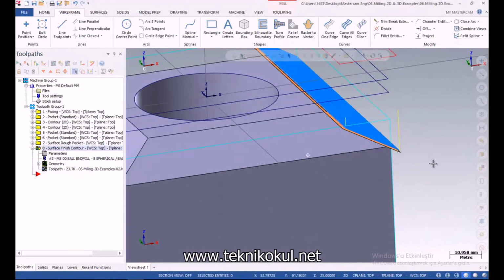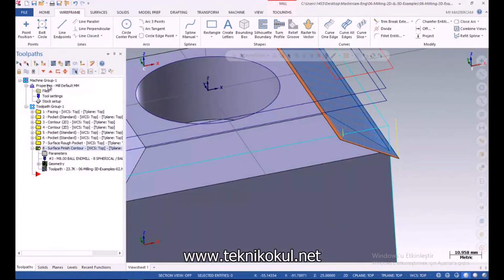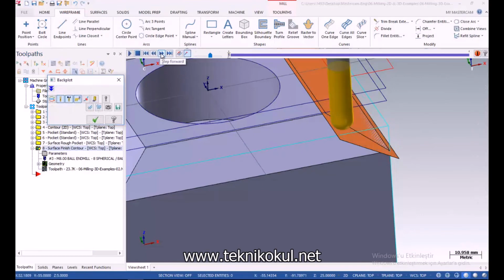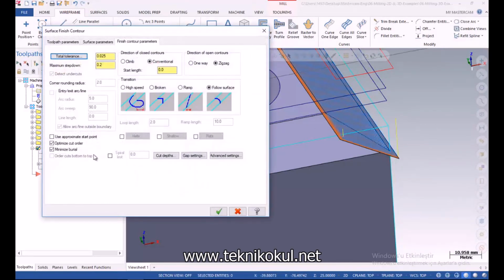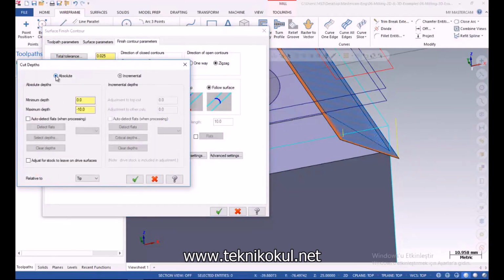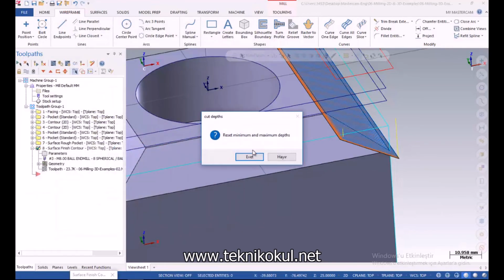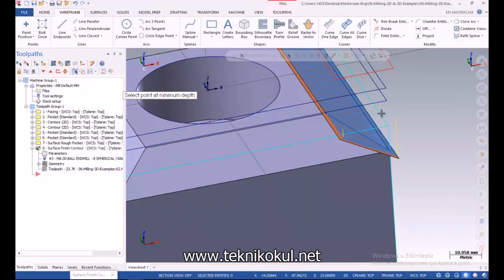Yeah, in that case, when I start my toolpath, as you can see, that can be Z 0.7 because you know that we extended our surface 2 millimeters. So if you don't like that, I'm gonna select cut operation. I'm gonna select absolute. I can write 0.1 minus. Let's select depth.